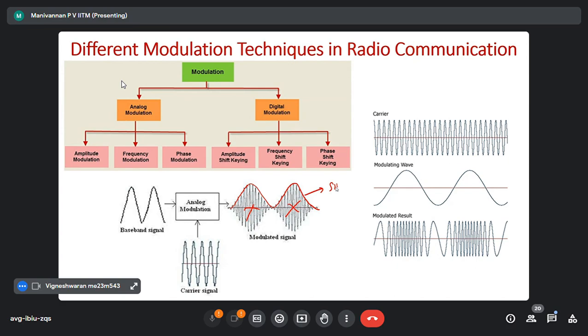The audio signal is given to the speaker or TV, the video signal is given to the screen. Cell phone, all this. This is what happens. The key point is that modulation is done only to reduce the size of the antenna, to a practical size, including in a cell phone, a few centimeters. That is why cell phones transmit in gigahertz. Original cell phones were transmitting in megahertz. Motorola made the first cell phone 30 years before, I have seen it.